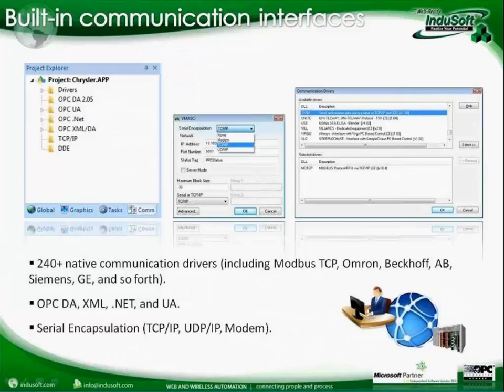Finally, for all the serial communication drivers, InduSoft has a built-in feature called serial encapsulation, which allows you just by selecting an option here in a combo box to encapsulate any serial protocol over TCP/IP, UDP/IP, or through a modem.